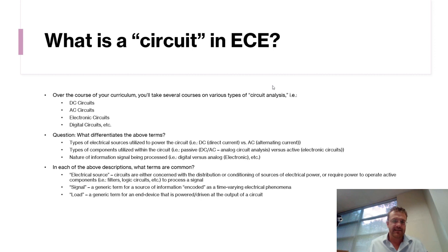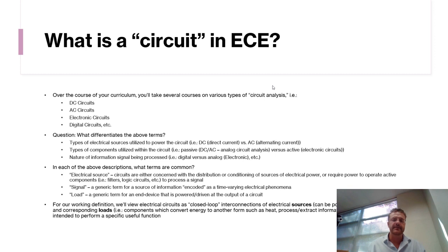What kind of information is it processing? Well, you want to dispense towels when it senses that a person is in the proximity. So there's some small sensor on the front that can tell whether or not a person is there. It's taking the information out of that sensor and using it to do the interesting thing. And what is the interesting thing in this case? Well, you want to dispense paper towels, so you're going to need some sort of motor to make that work. In that case, the load, the thing that's actually taking the power, conditioned on the information to do the interesting thing, is the actual motor that's driving the towel dispenser.